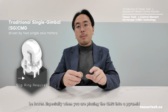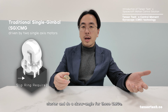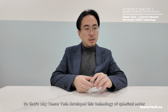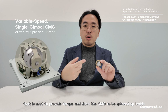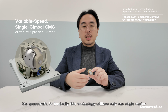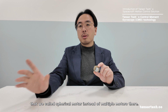Especially when you are placing the CMGs into a pyramid cluster and applying a skew angle to those CMGs, it will occupy even more space. So that's why Tensor Tech developed this spherical motor technology, which is used to provide torque and drive the CMGs to spin up inside a spacecraft. Basically, this technology utilizes only one single motor, which we call a spherical motor, instead of multiple motors.